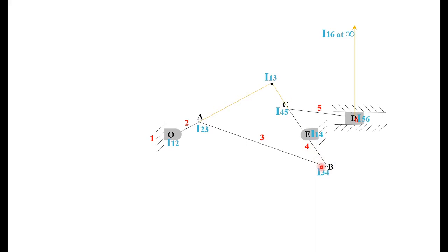Okay. And this will be equal to what? The velocity divided by the center distance will be equal to omega of 3 or omega of AB. So that is the expression you have to use. Here VA is known, and I13A and I13B, both distances you have to measure. Once you locate I13 in your diagram, you measure it and write it here. Then you will get VB.